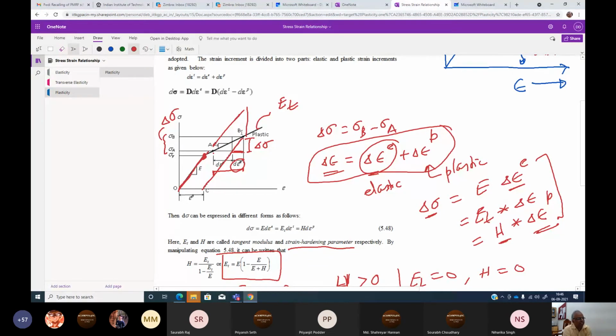So what does this plastic strain do? What is its job? The plastic strain basically accumulates in that material. As you are giving load and load, it will keep on accumulating. And this accumulation causes the fractures, maybe initially internal fractures, and later on you will see the fracture on the surface also. And they change the material.